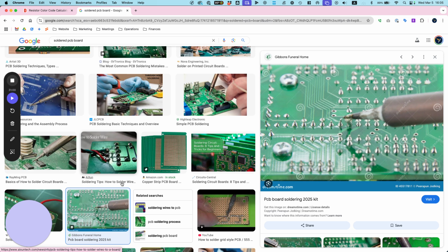Let's just verify because it has a gold band on it. So 390 plus or minus 5%. Okay, I'm going to turn this multimeter function to the ohm. Okay, it's just on auto. Auto is the ohm.